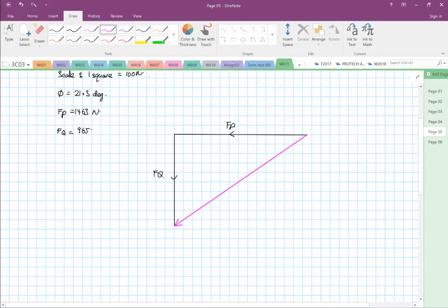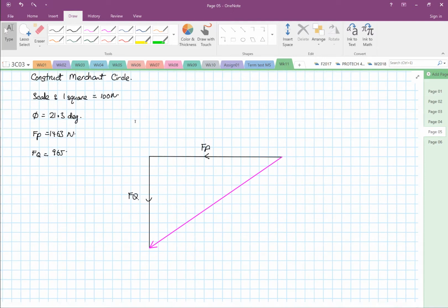Okay, so then I'm going to sketch out the positive rake angle too. So we're going to have a positive rake angle too. So we know that this is your R. Then I'm going to construct my positive rake angle of 10 degrees. So this is the cutting edge. This is my datum, and then I'm going to draw 10 degrees positive.